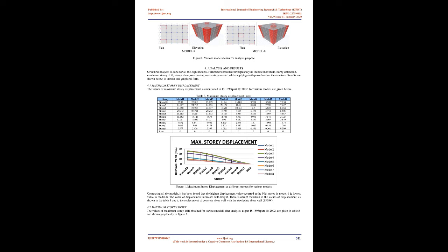3. Selection of grid dimensions and defining the material properties of the building section. Define material properties. Add new material properties data. 4. Defining section properties of the building section. Define sectional properties. Section frame properties. Add new properties. Choose concrete frame section properties data. 5. Defining the slab properties of the building section. Define sectional properties. Slab properties data.